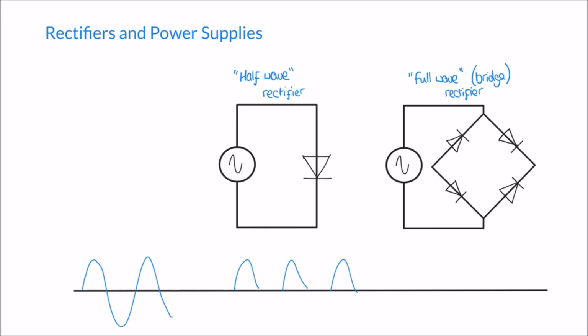As you can see, I've still got the positive elements of the waveform, but where the waveform was negative has been lost. So you can imagine that we've lost these negative half cycles of the waveform. This presents some disadvantages though, because by simply chopping off these bottom halves of the waveform, we've lost a lot of the potential energy that this circuit could provide. We've made these big gaps that appear in the waveform as well. So it makes the resulting waveform more of a pulse of voltages with gaps in between them.